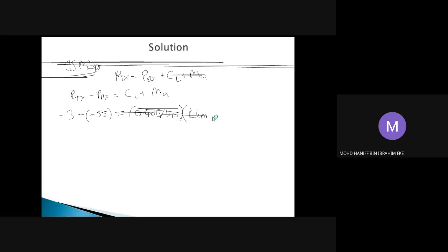Okay, 0.4 L kilometers here. Okay, and then we have the loss due to the splices. Since we have a splice loss of 0.1 dB per splice, and one splice for every kilometer, since we have L kilometers, we just need to multiply by L. This is the splice loss, 0.1 dB per splice, once for each kilometer.